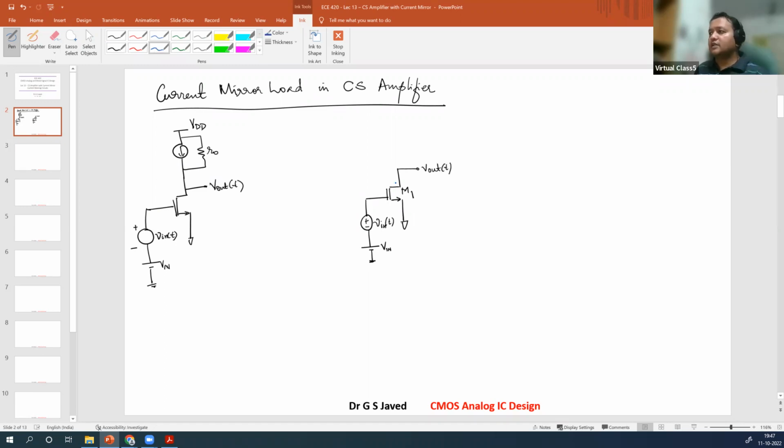Now this current circuit, you will have the actual mirror circuit. Since you are using it on the source with a VDD, you will use a PMOS device. So here you have the PMOS device present, where the current I that is present here will be expected to flow in this device here. So we will call it as M2. The VGS of this device is given here.